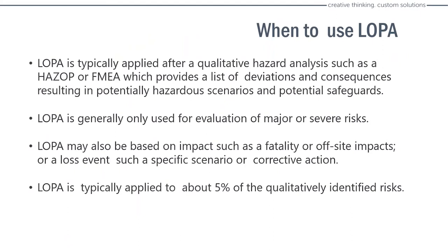When do we want to use LOPA? Typically applied after, as I said, a qualitative hazard analysis such as a HAZOP, and we're looking at the list of deviations and consequences related to potentially hazardous scenarios, essentially a PHA. It's usually used only to evaluate the most serious risks.